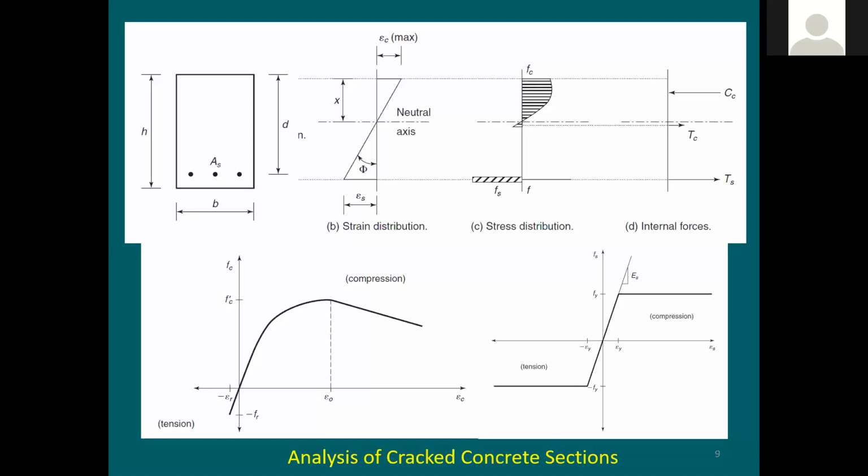It's going to be going up because usually it will try to be right in the middle, or the mid height, of the effective section. So if you start here with 24 inches, now all of a sudden after cracking this becomes 20 inches, the neutral axis is going to be at 10 inches from the top. It's going to be shifting up. It will never go down. So I'm expecting this neutral axis to be up there, right? It's going to be in the top half of the beam.